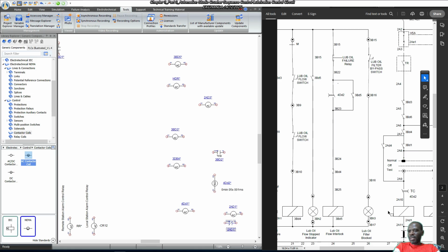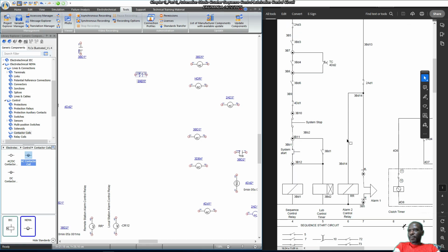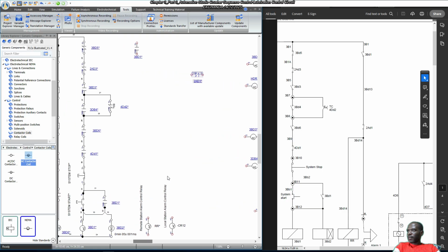You can think of this as a control relay, or as the coil for the power contactor, which is what we're thinking it is in this case. So when this power contactor, of which 281 is a part, is energized, this auxiliary contact is the one to de-energize the alarms. That is where 281 comes into play in this position as normally closed. So that's our 281.